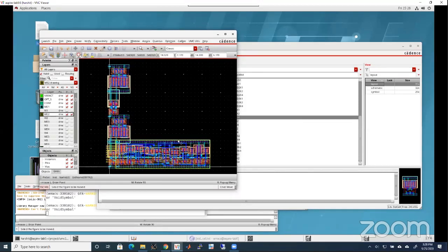Rule number 1: since NMOS is half the size of the PMOS, allocate 1/3 of that height to the NMOS layout and 2/3 of the height to the PMOS layout. Rule number 2: all the interconnections have to be done using metal 1 and poly. Do not use higher metals. Use higher metals only if absolutely necessary.